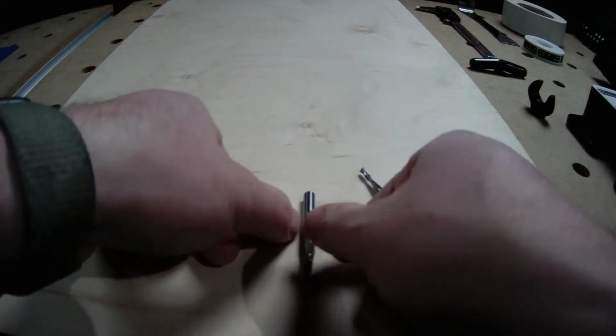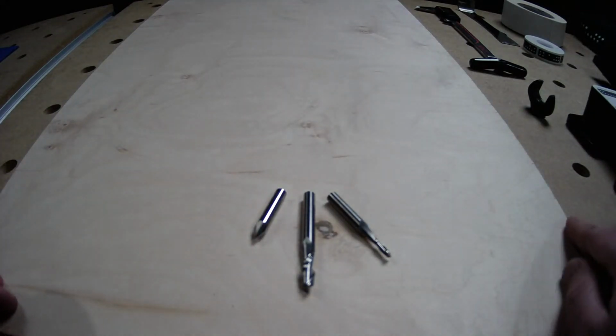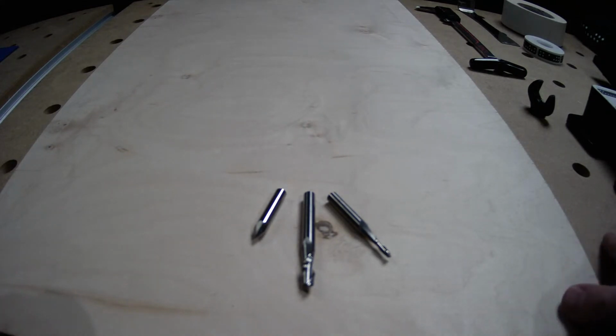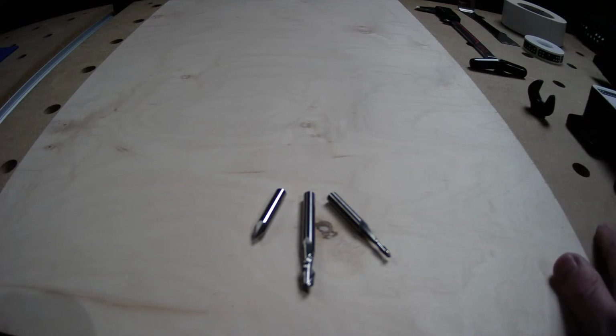Those are the 3 bits that come in the box with Origin, and we'll talk a little bit about feeds and speeds and care for your bits later on. These 3 bits ought to set you straight for a good amount of time. But this is definitely a consumable you're going to want to pick up a few more of. I'd say before you pick up Shaper Tape, you probably are going to want to pick up at least 1 of each the 1/4 inch and 1/8 inch cutters. The engraving bit really lasts a long time. I don't really see any reason, unless you drop it and break it, or it really is starting to feel dull, that you should replace that one or feel worried about it.